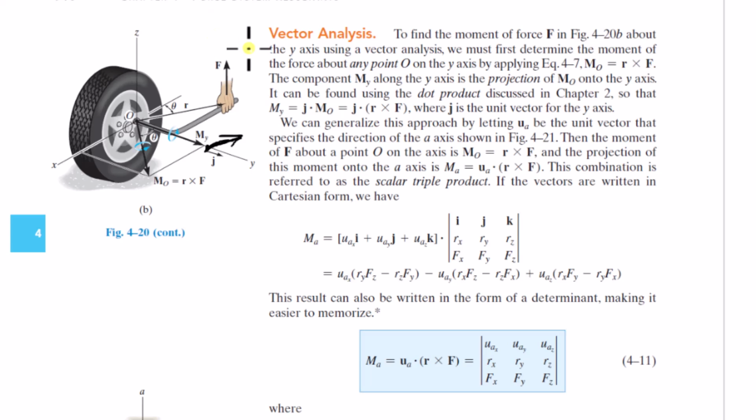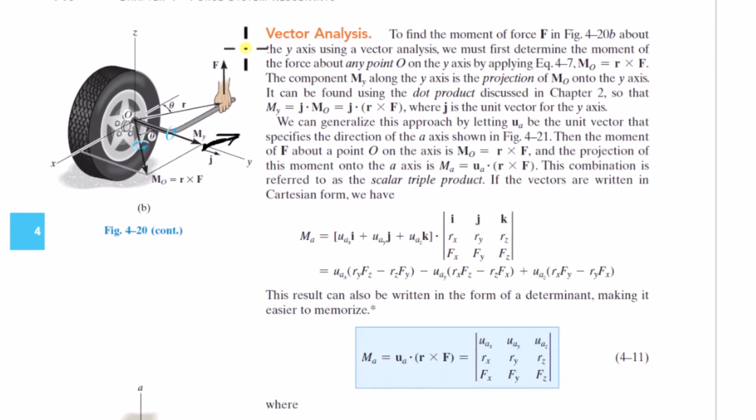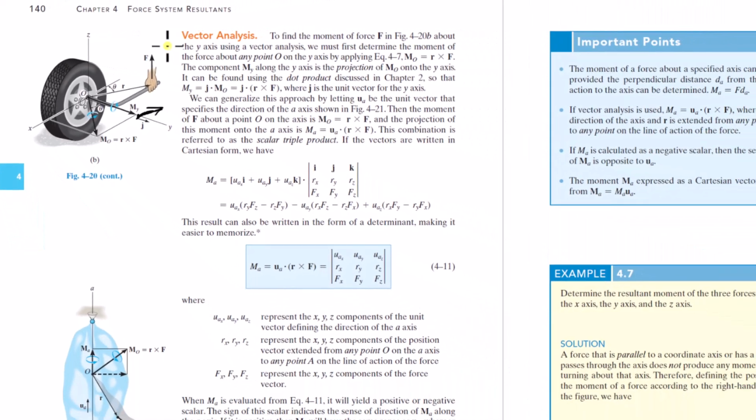The whole idea of transmissibility of a force, sliding vector, free vector, is that if you can move it in the context of the problem, you can slide that vector on the line of action or move that vector in 3D space, and you're not changing the statics problem. That's the idea.